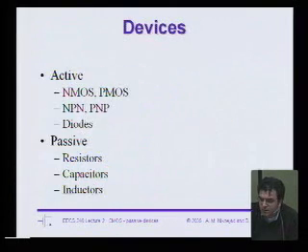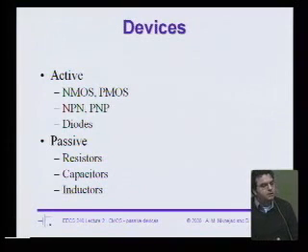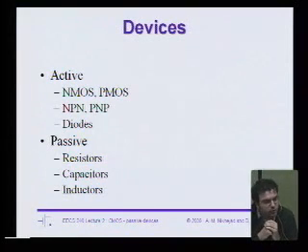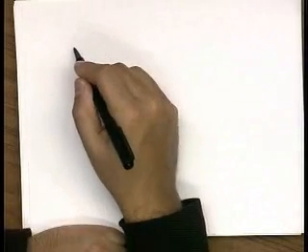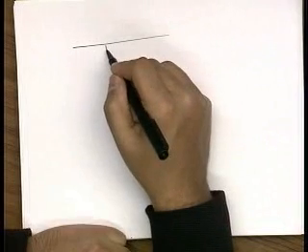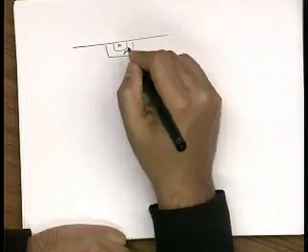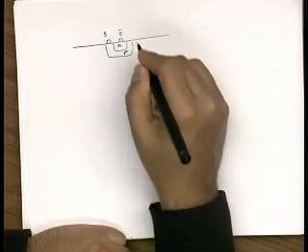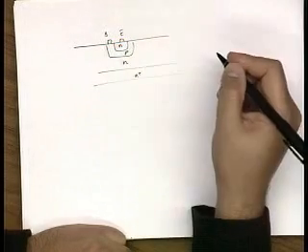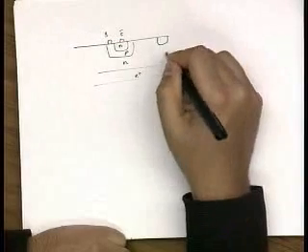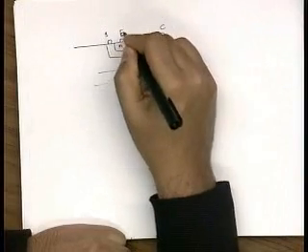Okay. So very quickly, let's talk a little bit about why in a traditional CMOS process you don't have good bipolar devices, right? So intuitively, it seems like you should, right? If we look at a specialized process, let's say this is our N, this is our P, this is our base contact, this is our emitter contact, and we have our subcollector here. This is N+, so this is again N. And so it's a vertical structure, and this is our collector.